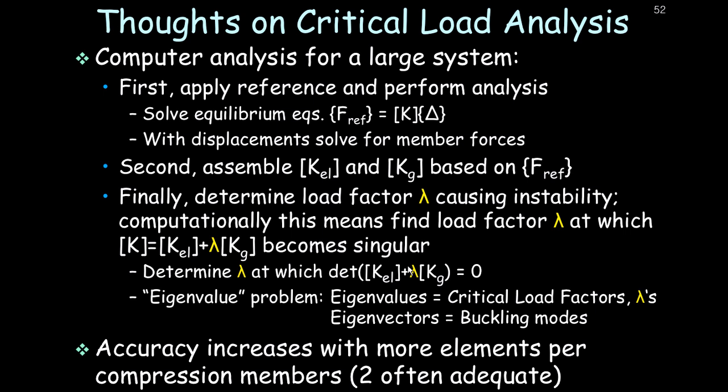Now, if you have a buckling shape that's a serious sine wave and it's very tight, you will not be able to represent it properly with just a single cubic polynomial. So you might need a few elements. Now you're breaking it up, splicing together a few cubic polynomials to sit right on top of that sine wave, or sine and cosine wave, that's the actual buckled shape. So that's why you might need a few elements to get there.